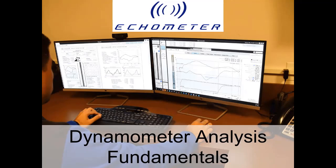What you see on the left screen there, if you can see that, is a portion of the dynamometer report where we can understand multiple points of the system, not only how the pump is pumping, but also how the rods are loaded and about the pumping unit itself. How is the structural balance? How much torque we have in the gearbox. So we have a pumping unit that is designed to lift some weight. So structural capacity is one thing that we need to focus on. We want to make sure we don't overload the pumping unit.